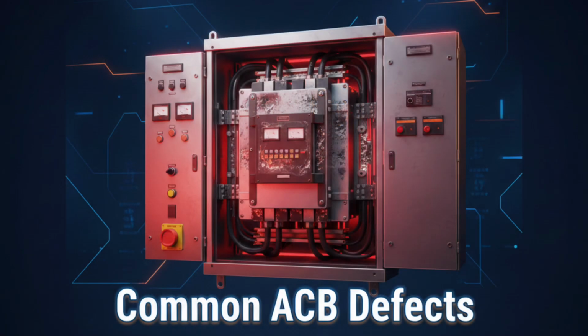Common defects in ACB. Common onboard problems include: breaker not closing, possibly spring not charged, UVR not energized, or protection active. Breaker not tripping: trip coil failure or mechanical latch jammed. Spring not charging: motor failure or mechanical issue. Frequent nuisance tripping: wrong protection settings or faulty CT. Contact erosion due to repeated heavy faults. Overheating terminals from loose connections. Burning smell: possible internal damage. Regular inspection prevents major failures. Never ignore minor abnormal signs. ACB failure during a fault can be extremely dangerous.